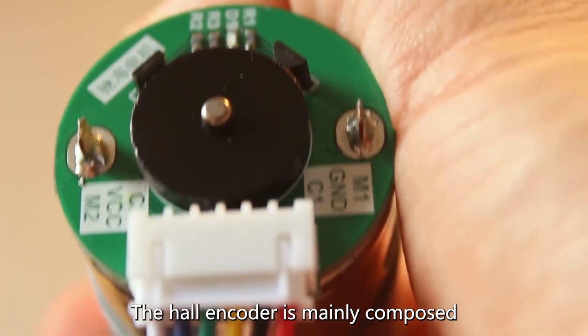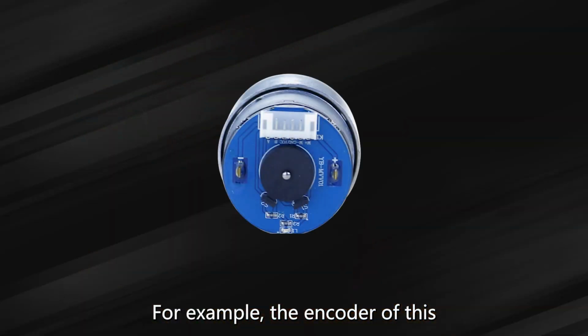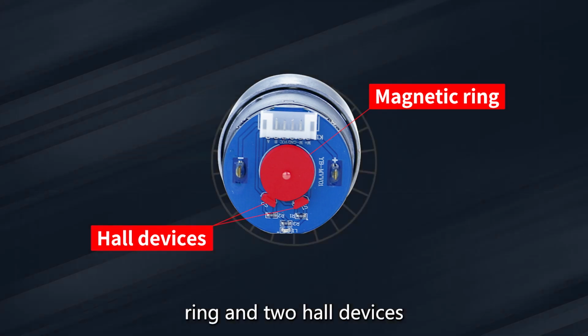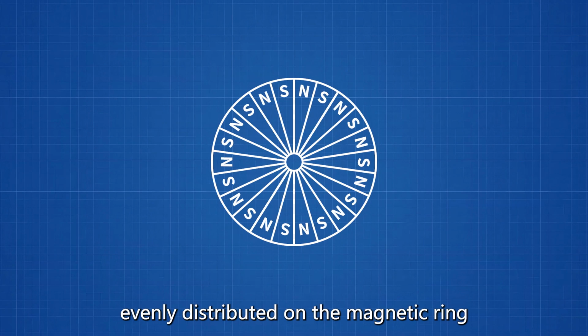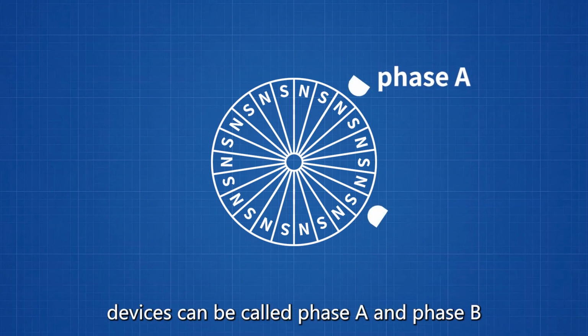The Hall encoder is mainly composed of a Hall device and a magnetic ring. For example, the encoder of this motor is composed of a magnetic ring and two Hall devices. Its magnetic ring has 11 poles, which is equivalent to 11 graded magnets evenly distributed on the magnetic ring. The data obtained by the two Hall devices can be called phase A and phase B.